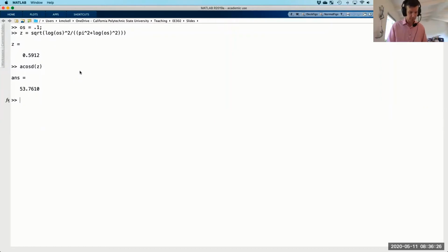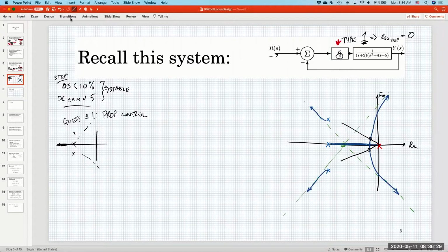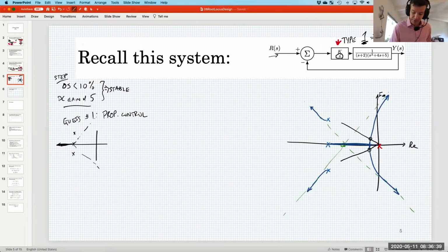Okay. So is an integrator for when you want the output to match the input, basically? Well, yeah, the presence of more integrators in the controller is going to necessarily, at least as long as you have unity feedback, increase your type number. Increasing your type number will increase the range of reference signals that you can track perfectly in steady state. Did you understand that summary?